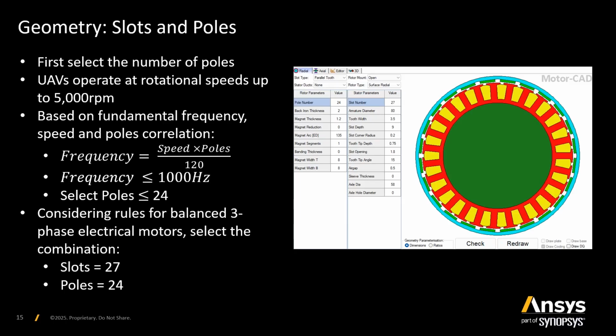But as well, in a specific configuration, we can energize only one third of the machine, or if one third of the machine fails, the other two thirds will continue operating. This is essential for drone applications. So it's always important to select a configuration that will allow the vehicle or the drone to operate, or the motor to keep rotating, even though there may be failures in some of the coils, possible short circuits, and so on.